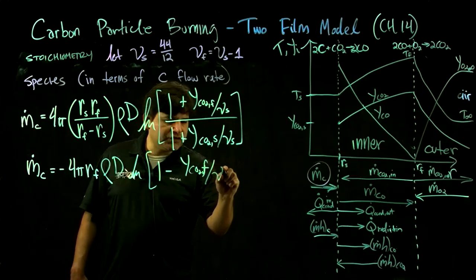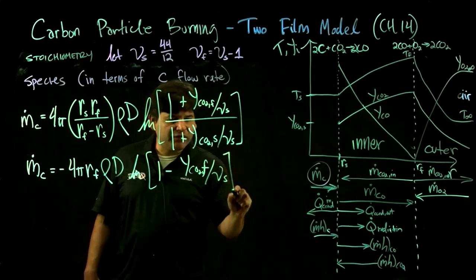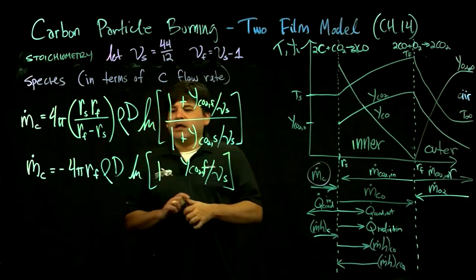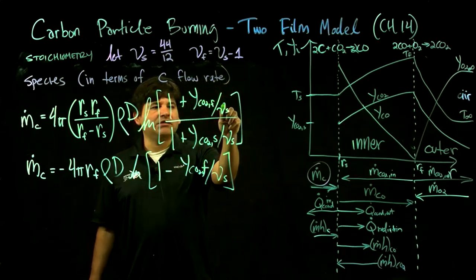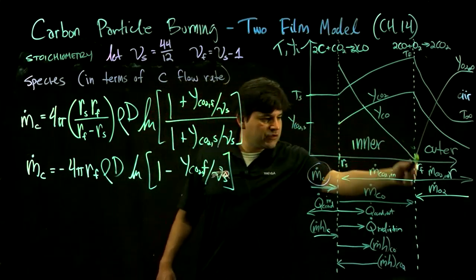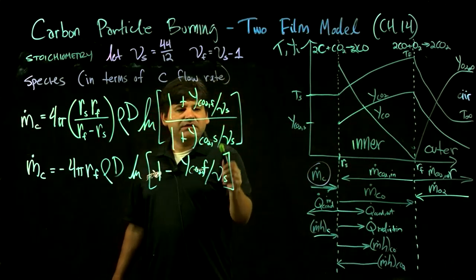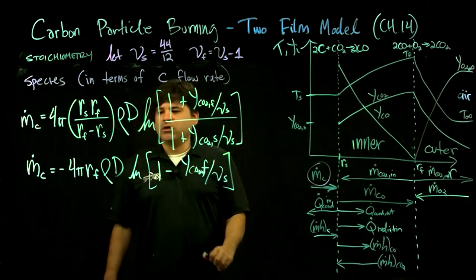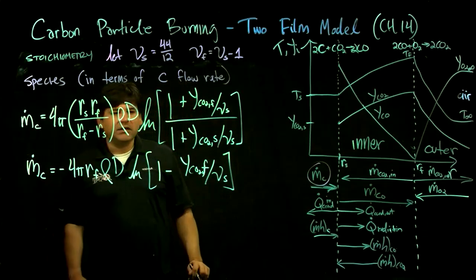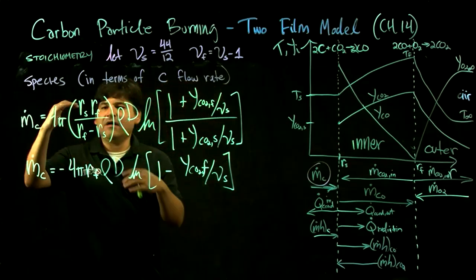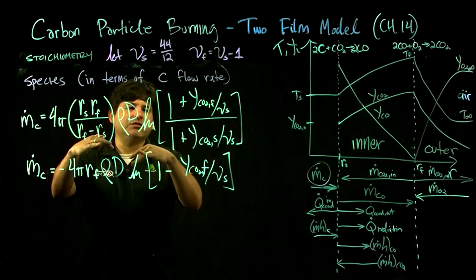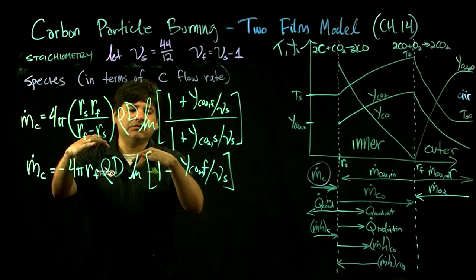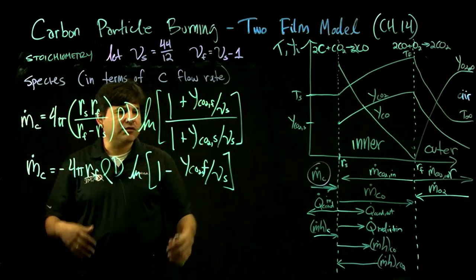Whatever the concentration of the flame is, and then the surface. So I guess they're minimizing. It probably does give you some dependence on the flame stoichiometry, but we're simplifying this only in terms of the surface stoichiometry. But nonetheless, we now have two equations for the mass carbon, and that helps us to solve the problem for any of these variables that we might need.